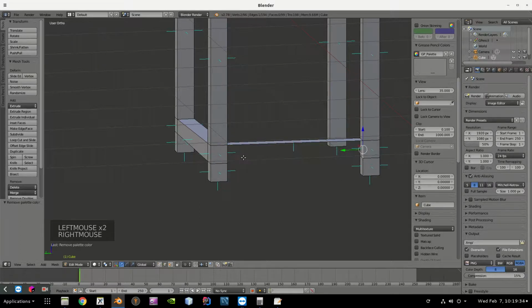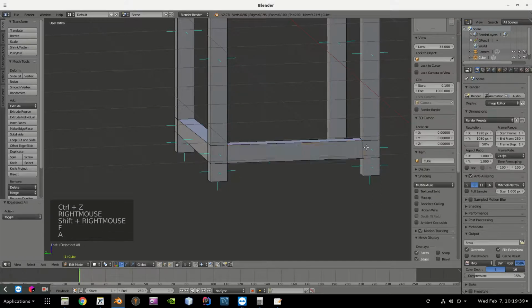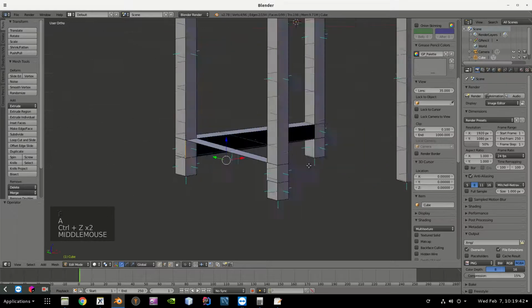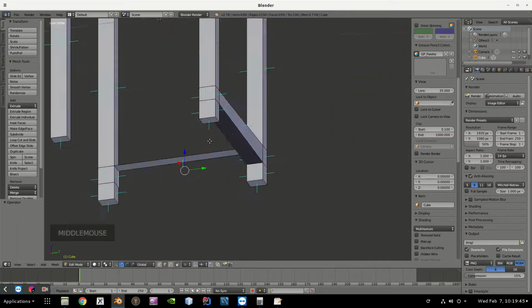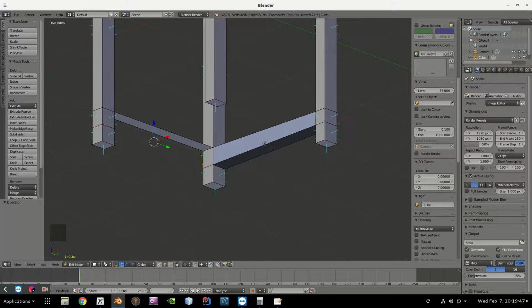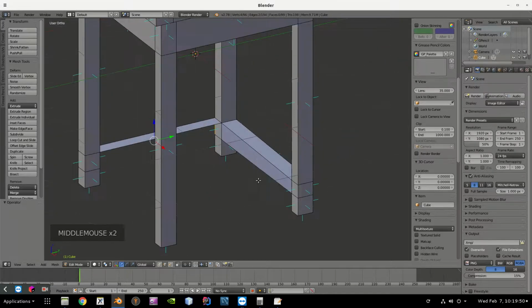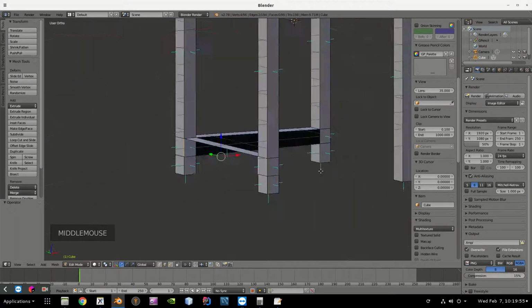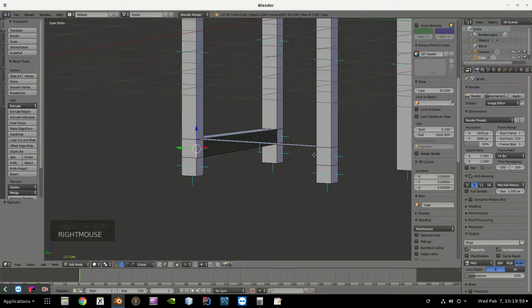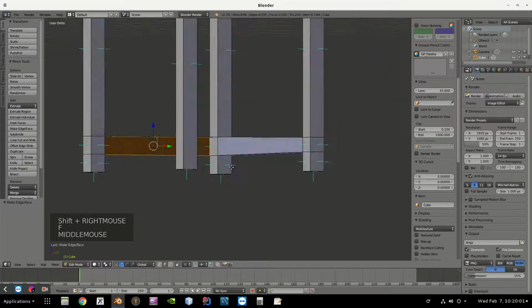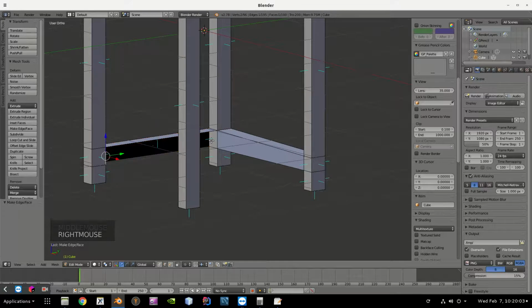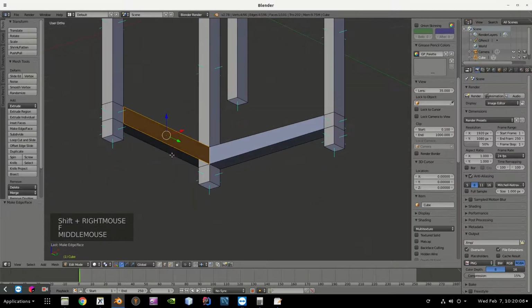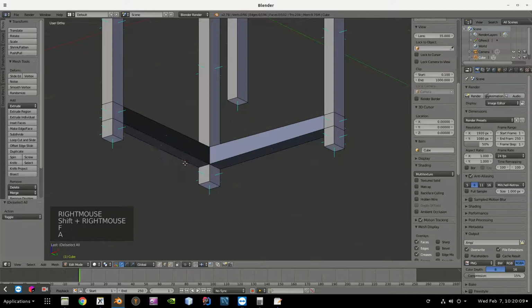So this edge and this edge, if I join them, they work. These two. Now they started working in all the cases. It's kind of strange. However, we still got a problem for these two ones, right? The surface normals are going inside, not outside the way they should. So there will be many different scenarios where you join faces like this. Sometimes they will work and sometimes they won't. Let me try to finish this off. See, this is again wrong. This one is wrong again because these surface normals should be sticking out.